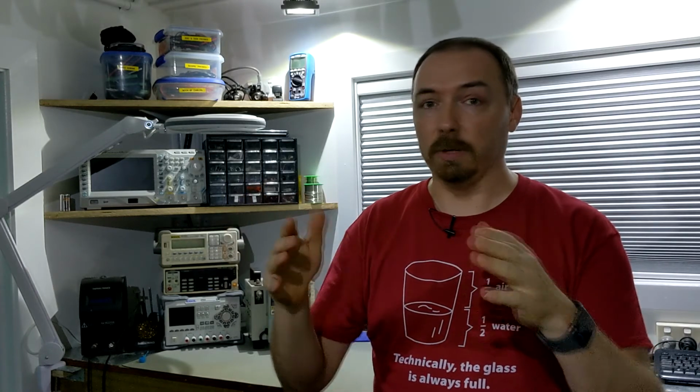Then I take that design and make sure that it can be manufactured properly, that if it's an injection molded part, that it will pop out of the mold. If it's a sheet metal part, that we can manufacture in a way where we get the most out of a whole sheet, like stamping or cutting. That's what I do.